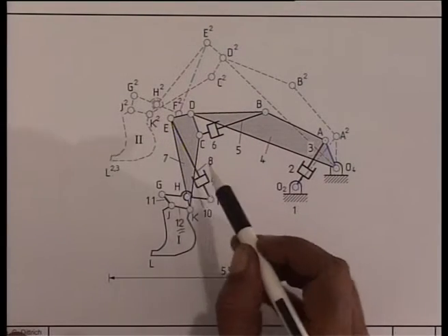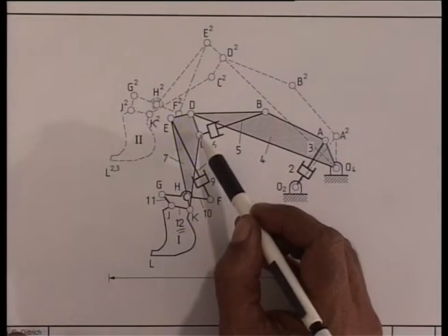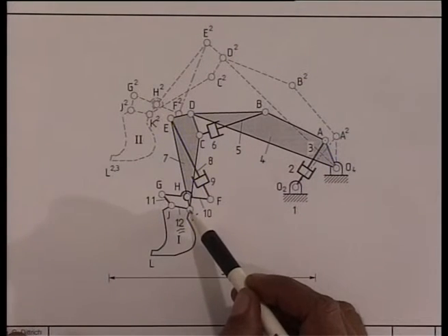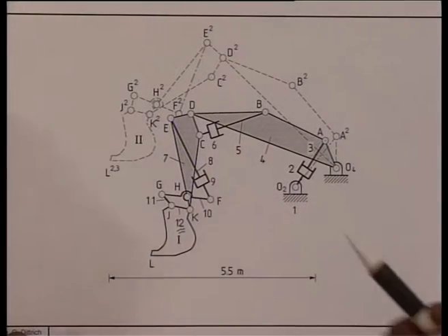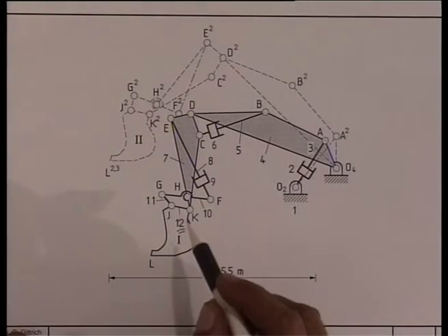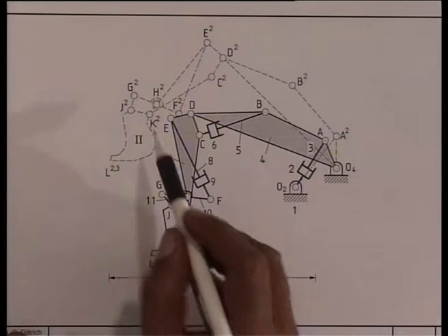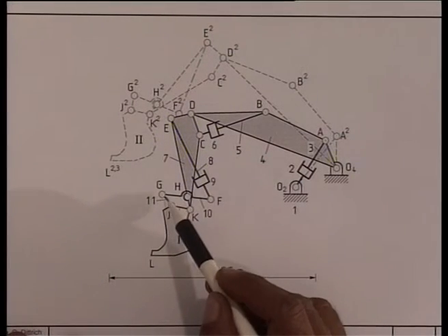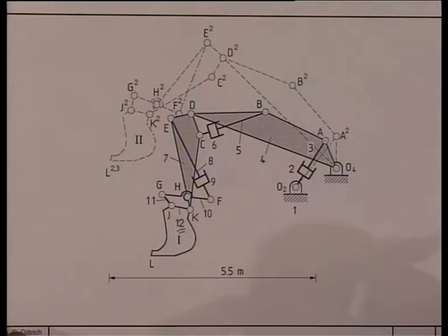Link 7 has 5 hinges on it, C, D, E, H and K. So, this is a link of 5th order. The question is, when this J and K move to J2 and K2, can we locate the corresponding positions of all other revolute pairs? To solve this problem, first we note that